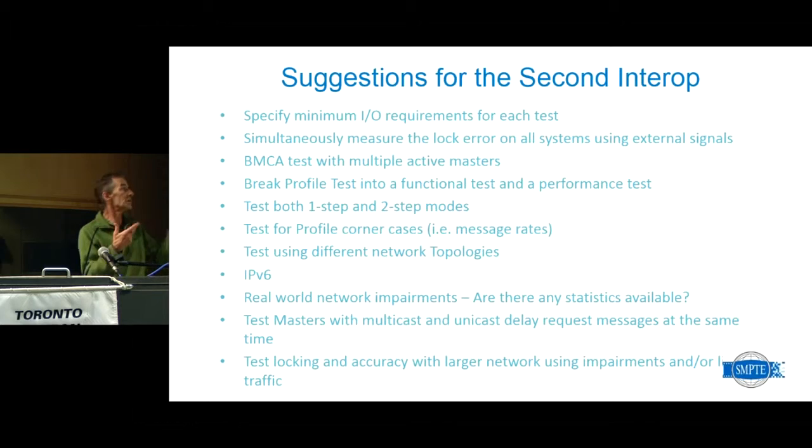Did you know that the one thing missing from PTP is you cannot tell the slave if you're a 59.94 or a 50 hertz plan? There is no mechanism. So this sort of stuff had to go into the profile. So receiving equipment says, oh yeah, I know I'm in Toronto, I know I need to make 59.94, not 30 or 25 or whatever.